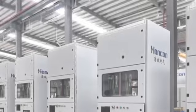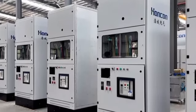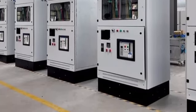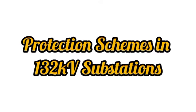Outgoing power distribution. Power is sent out to either 132 kV transmission lines or further stepped down to lower voltage levels, 33 kV, 11 kV, for regional or local distribution. Control and monitoring. The SCADA system allows real-time monitoring and control of the substation, ensuring operational efficiency and rapid fault detection. Protection schemes in 132 kV substations.